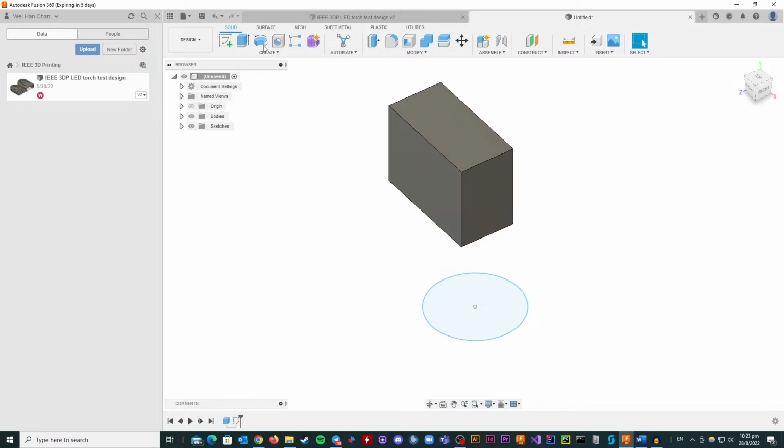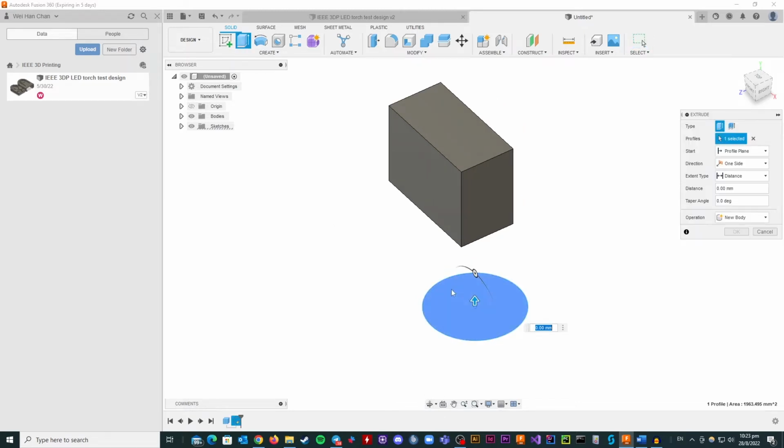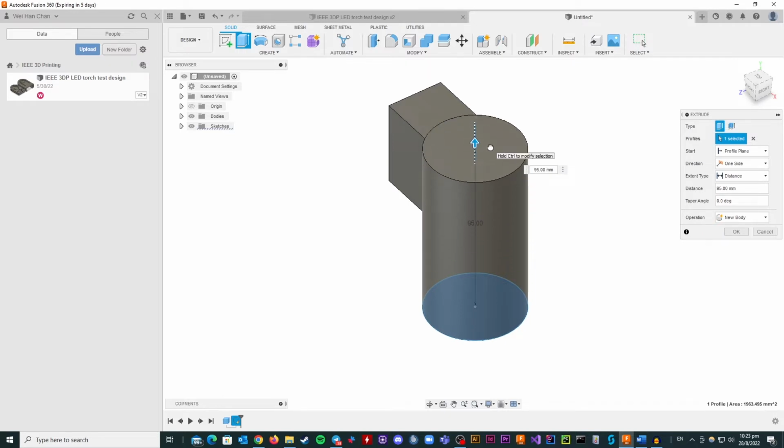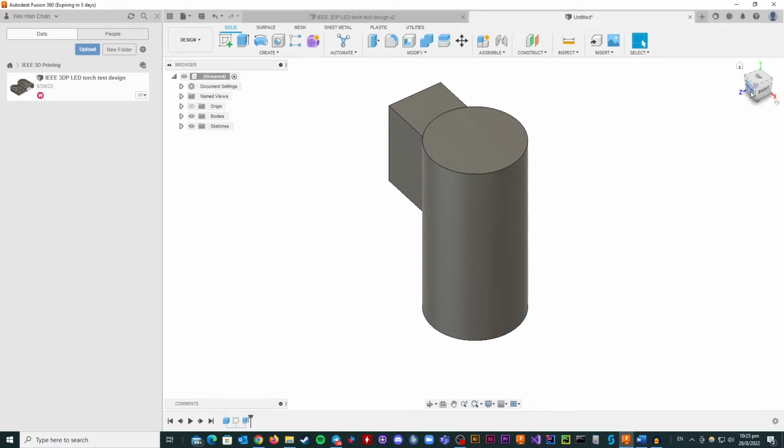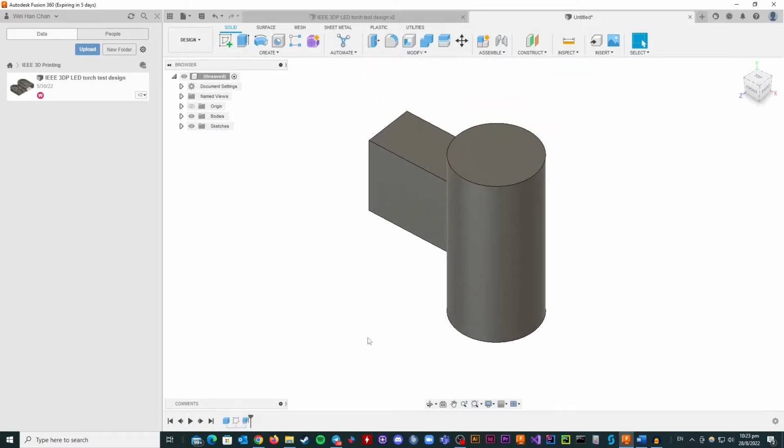And what you want to do afterwards is to use extrude, which converts your drawing into an object with a 3D profile. So let's say you want to go for 100 millimeters. You can even mouse your way up there and select OK, and this is where you have your object.